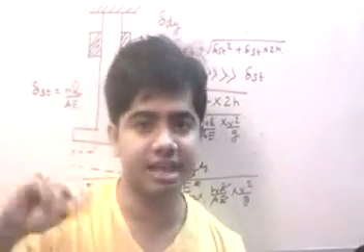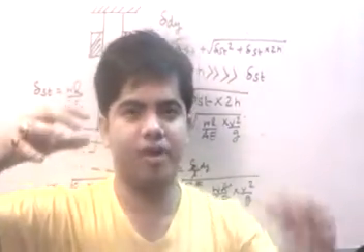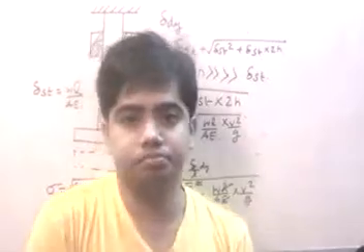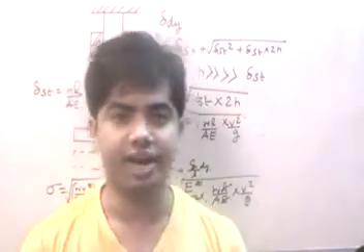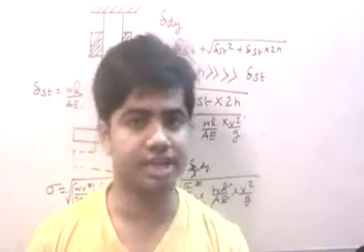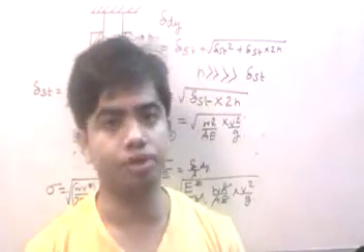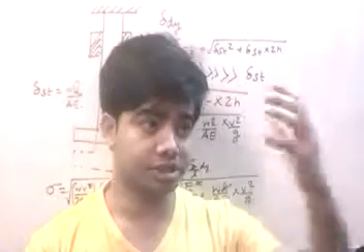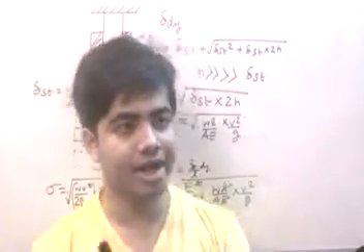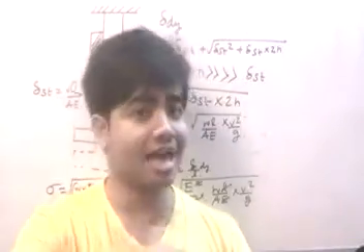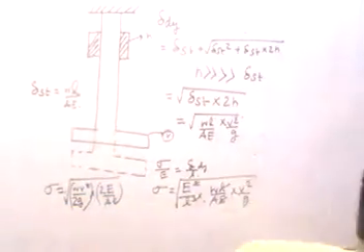There is a slow incremental increase of load, right? But in dynamic loading, it's like this. The weight falls bang on the bottom flange with some velocity and it is deflected, right? And I have the stress in the bar to be directly proportional to the kinetic energy of this falling weight, right? Now let us see a case wherein we get the two, static and dynamic loading. Let us see that.